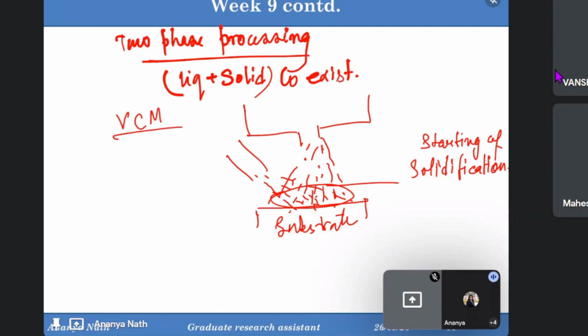So here we are just adding some salts. In case of TiB2, we mix KBF4 and K2TiF6 to get the TiB2. The other components or compounds which are formed, we can just separate out as a slag and remove it to keep the TiB2 only in the melt, and that will give us a good reasonable property of the metal matrix composite that we are aiming for. So TiC, SiC can also be formed using the same process of this type of in situ processing.